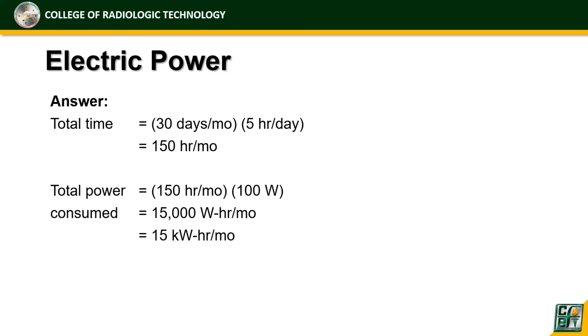So the problem asks how much will it cost? Magkano? In order to get the total cost, the total power consumed times the rate per kilowatt hour. So 15 kilowatt hour per month times 10 centavos per kilowatt hour.